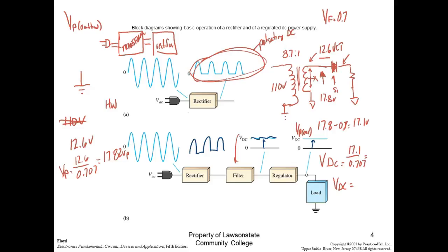So Alabama Power outputs a perfect sine wave at the source, but then it's got to go through all these transformers down there. And then, of course, what happens is you have line loss. You have resistance in the wire. So people don't understand that. Your air conditioner kicks on, and then your lights dim a little bit. It's because of line loss. You might be a pretty good distance away from your transformer, right? A lot of people have 3 or 4 houses hooked up to the same transformer, and some of those down drops can get pretty long. Or you might even have a loose connection out there.